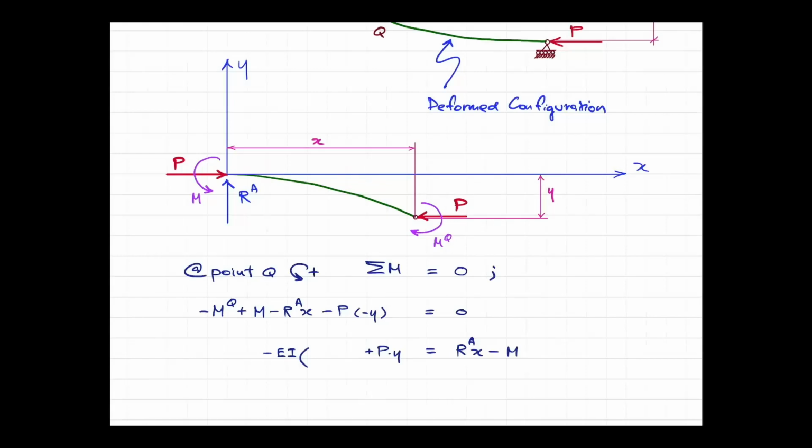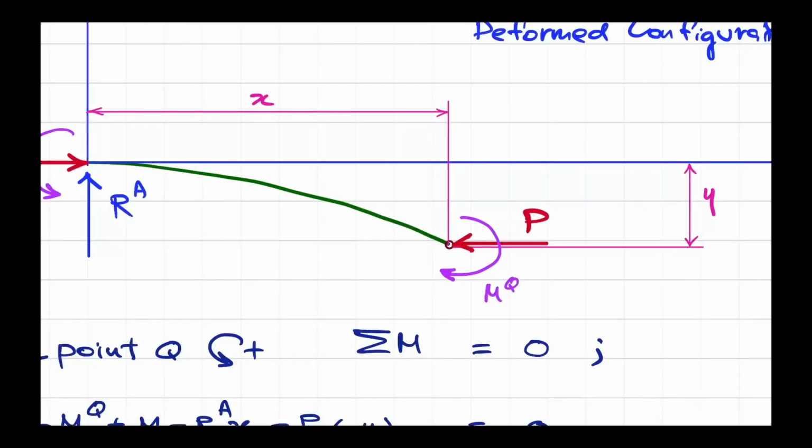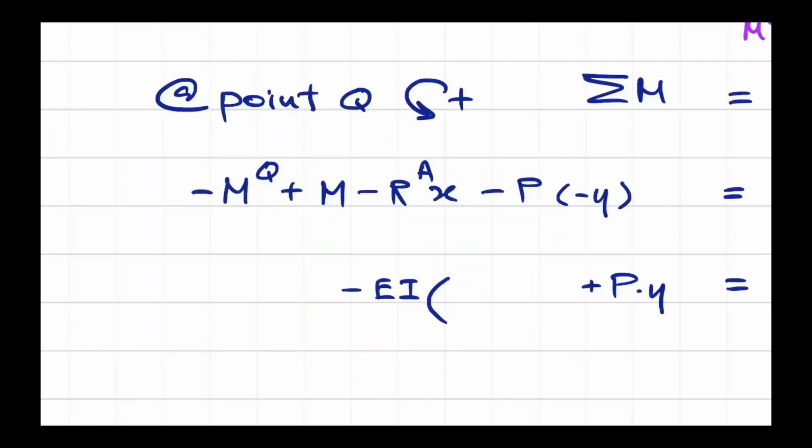But if you look here, this curvature is a curvature that causes your beam to go like this, from positive slope to 0 to negative slope. That is the negative curvature. The negative value will change the thing in here, right? So we need to put the minus sign in front of the derivative of y with respect to x in order to neutralize the sign that you have from this curvature.